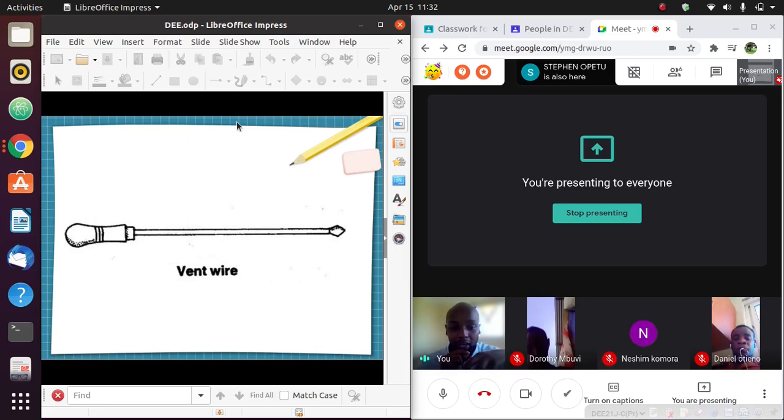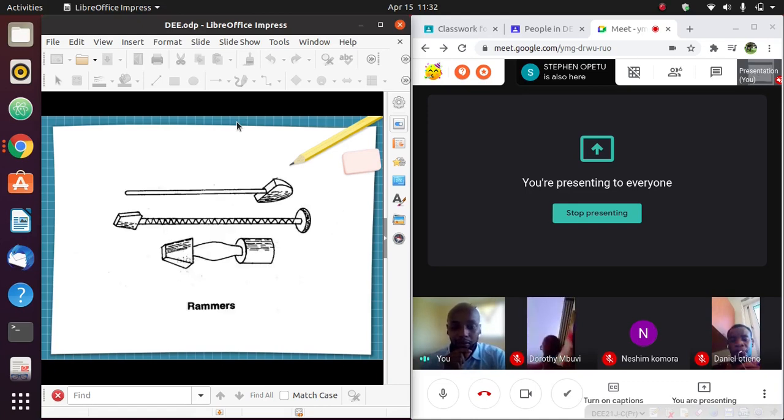And what happens when they expand in that mold? They will break it. The mold will start to break. That means that your casting, once the molten metal solidifies, will have a problem. It will have defects. So once you're doing that assignment, look at the defects that are formed once you don't vent the sand.